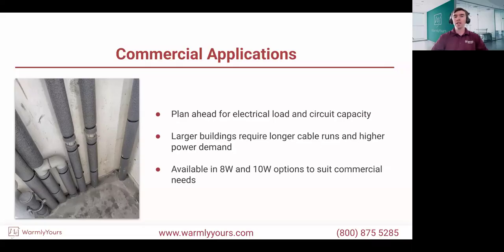But mainly how I like to talk about this, mainly why we're trying to get all this, is because if you're familiar with the concept of calculating the heat loss for a home, it's the same thing, right? We're trying to determine how much heat we're losing here to maintain that flowing state. And we're then simply trying to match or overcome that with a heat tape. So if we know this pipe is losing about 5 watts per foot, we're going to get you a cable that maybe delivers 8 watts per foot or 10 watts per foot. And that's how we approach this type of quoting process.